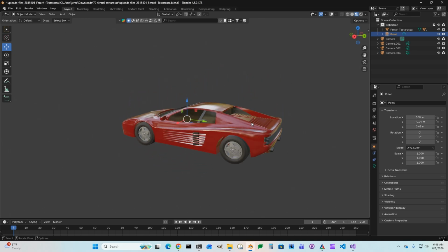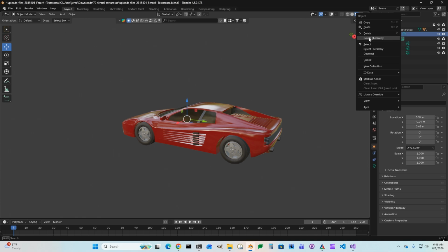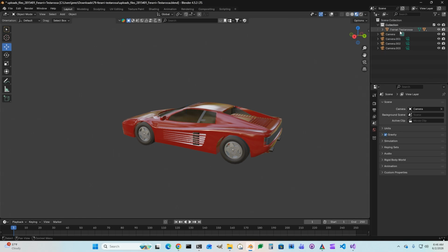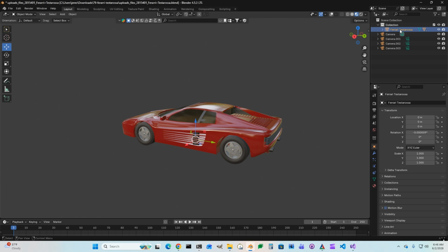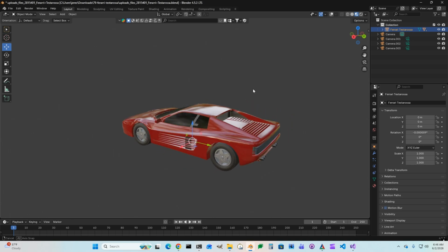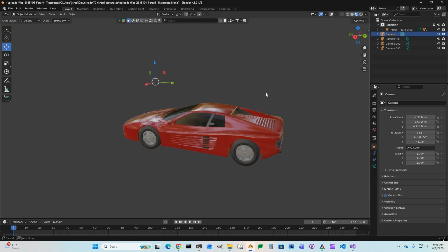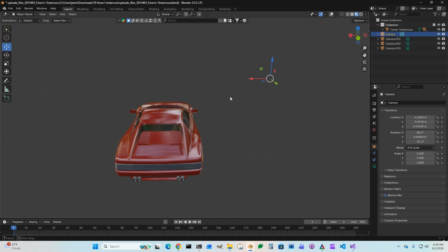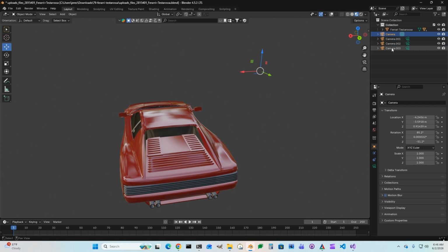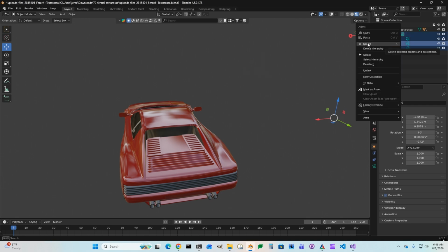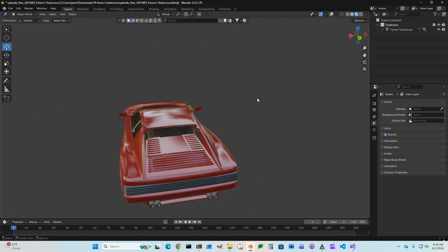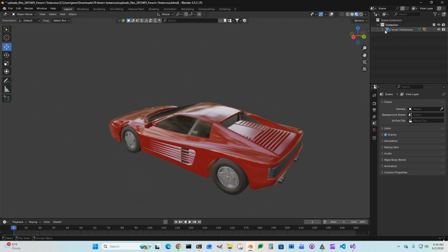The key principle to keep in mind is that any hierarchy modification should result in a scene graph that remains an embedded subgraph of the original hierarchy. In practice, this means that we can add or remove nodes, but we should not alter the parent-child relationship of existing nodes. For this particular model, we remove all camera nodes and the background reflection objects.